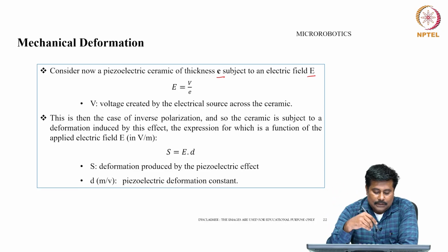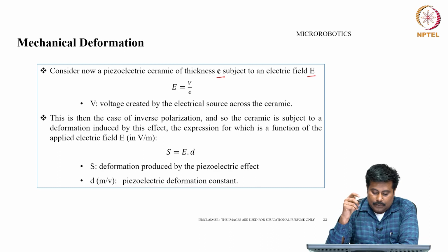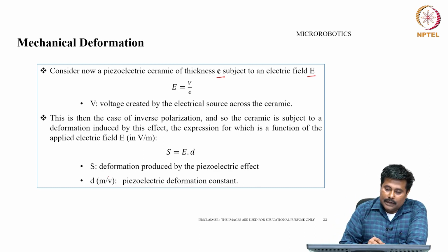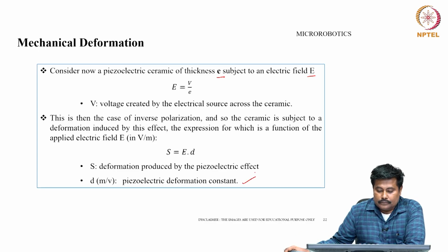This is the case of inverse polarization, so that the ceramic is subjected to a deformation induced by this effect, the expression for which is a function of the applied electric field E, represented in volt per meter, and S equals E dot d. Here S is the deformation produced by the piezoelectric effect, and d, in m by V, is nothing but the piezoelectric deformation constant.